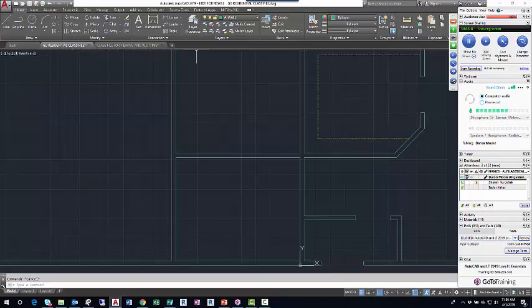I'll just use the offset command. I'll go offset 1 foot, enter. I'll left click the top horizontal, move down, and left click the left vertical of these 2 lines, move left. So those 2 lines represent a shelf. I'll just use the fillet command or trim command or whatever just to neaten up that line work.